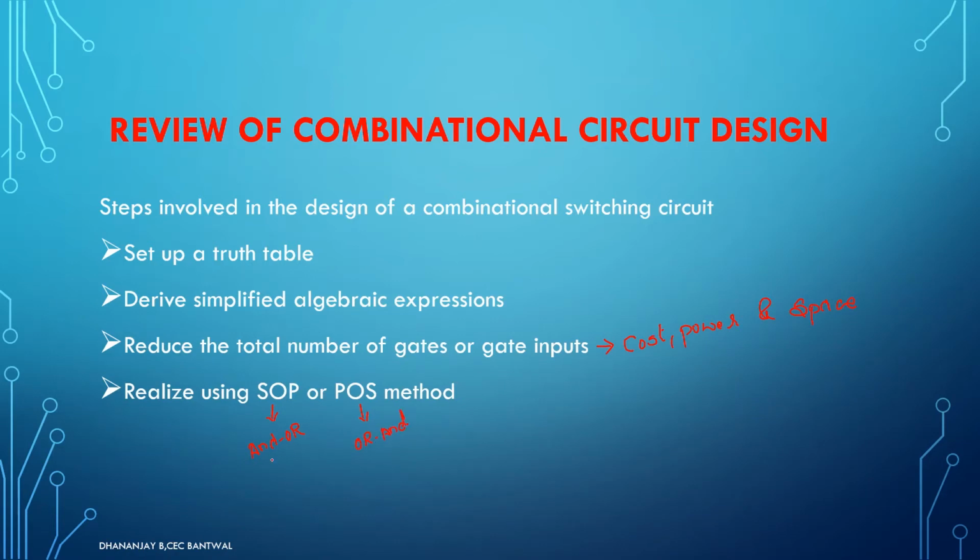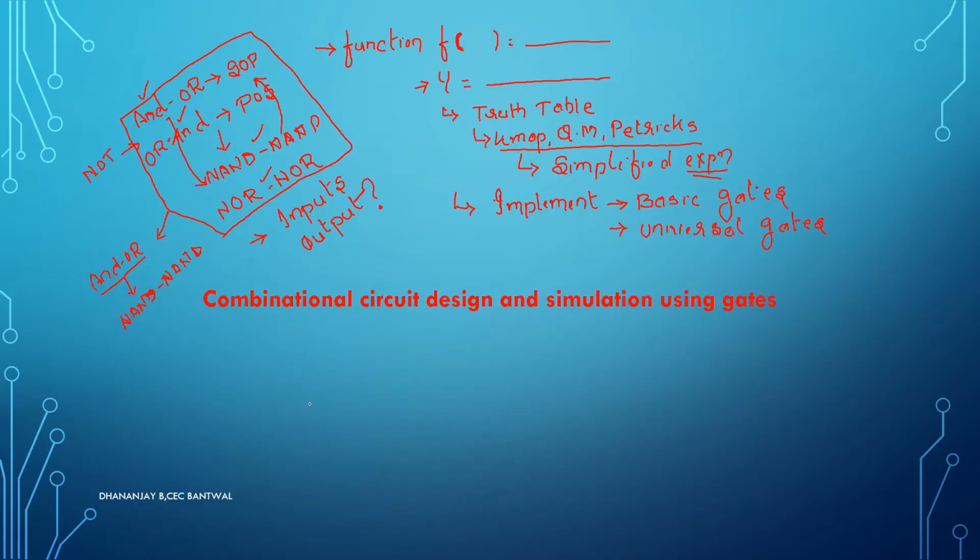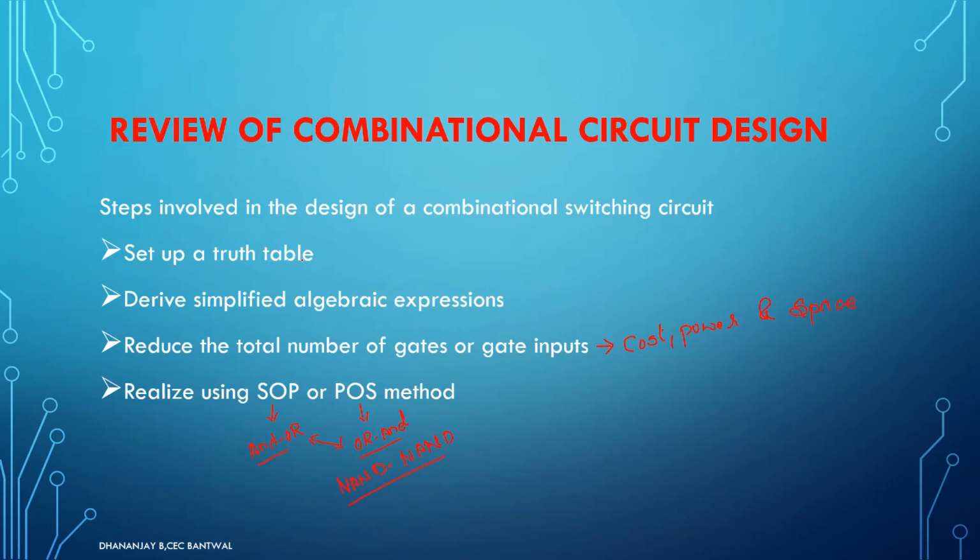As I said, this is not ultimate. You can interchange it. If you rig up a circuit using OR AND combination and want to write it using AND OR combination, you can. Or if you don't want to use any of these combinations and want to write it using NAND NAND combinations, that is also possible. This is what the steps are explaining here. This particular step has been explained to you previously also. In the previous slide, I explained how the particular circuit will be rigged up. The same has been given in terms of points.